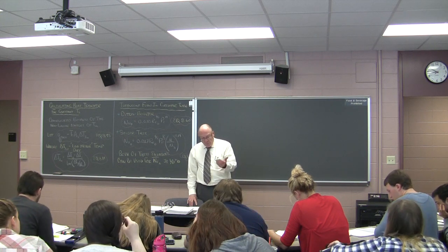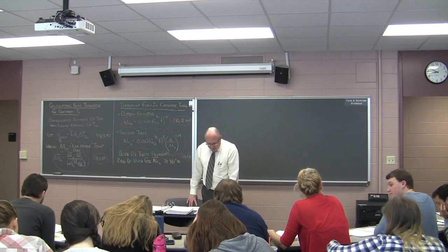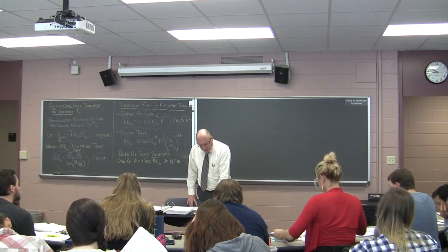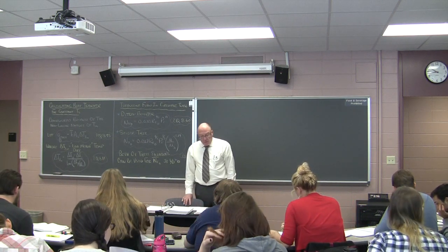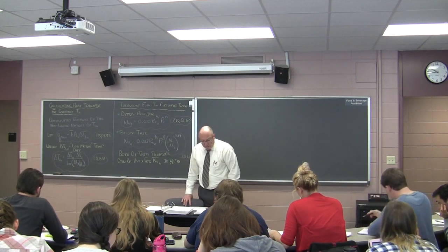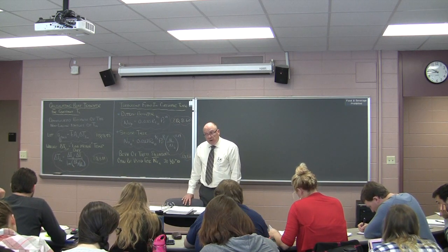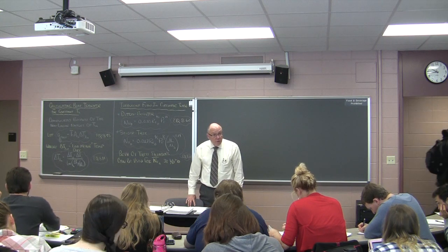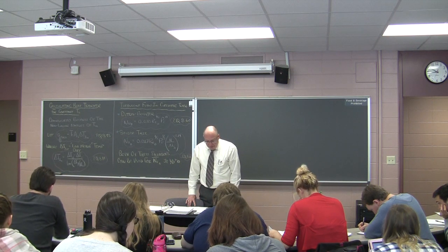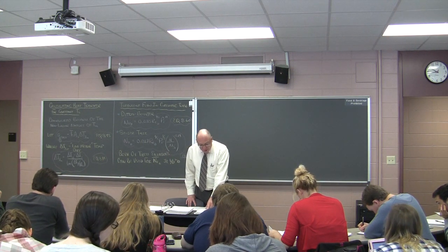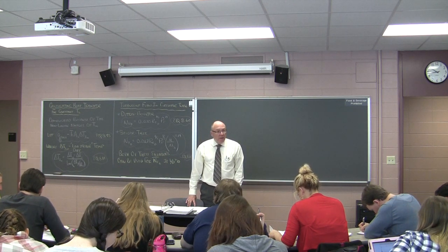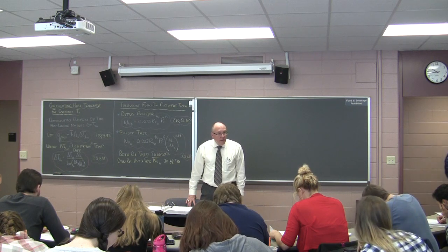So, we're going to talk a little bit more when we do our review coming up, but I want you to take a look at table 8.1. These are all different configurations for fully developed laminar flow, and for each one of these configurations there is a constant value of the Nusselt number, and those constant values of the Nusselt numbers are shown right there. And these Nusselt numbers are all calculated on the hydraulic diameter, which is equation 8.66. Now, it might be useful in your homework. Any questions?